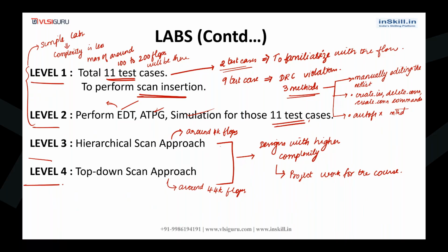Same way with ATPG, there will be a flow. If you want to do ATPG, you need to follow certain steps, so we'll understand the flow of ATPG. In our labs, we will be generating the patterns for the stuck-at fault model, the transition delay fault model, and the IDDQ fault model.